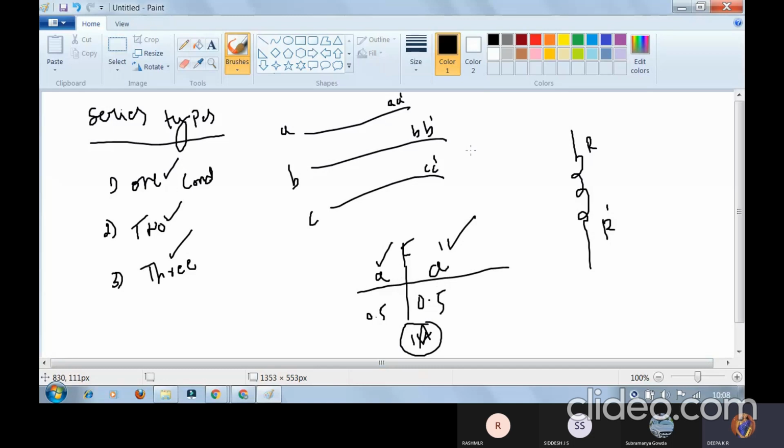But finally, we are going to check whether the system is getting the current. Where is the problem? Where does the fault exist? At the same time, when you consider any machines, unbalanced current flowing in rotating machines will cause a major issue called harmonics. That is why calculating the current is very, very important. Particularly, a rotating machine will have harmonics, which will heat up the machine within a shorter time. So heat losses will finally cause a short circuit fault. If the heat increases, we say immediately stop the operation of the machine, or else isolate the machine from the healthy devices.